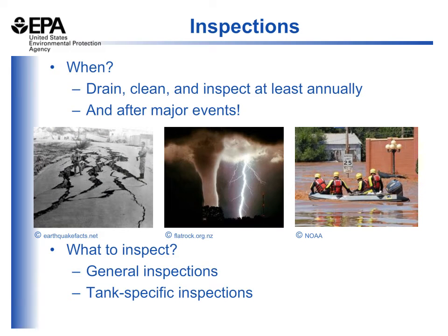And next we'll talk about inspections. We'll talk about what you need to inspect and how often this should take place. You're going to want to inspect at least annually or after any natural storm event. An example would be an earthquake, and that sounds pretty obvious. Or if you've had a large rainstorm, there may be some flooding, and it'd probably be a good opportunity for you to inspect your tanks and make sure everything's looking good.